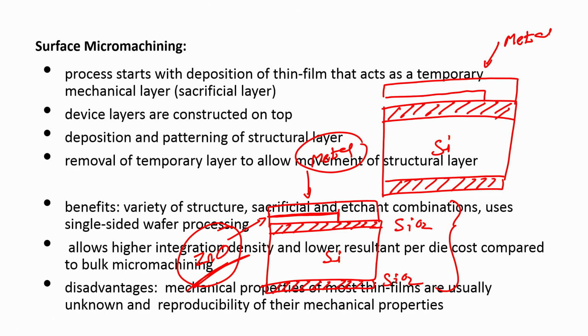the zinc oxide will get etched. Zinc oxide etchant will not affect the metal, which is, let us say, gold. Zinc oxide etchant is 1% HCl; 1% HCl will etch zinc oxide, it will not etch gold. So, this way I am able to fabricate a cantilever.